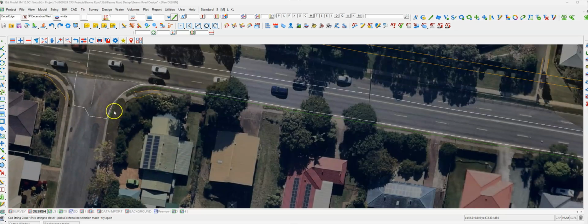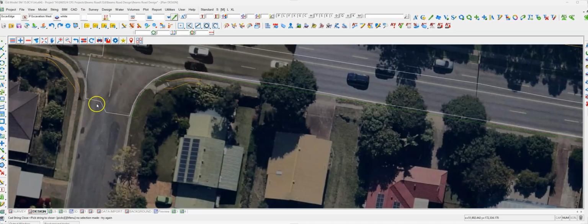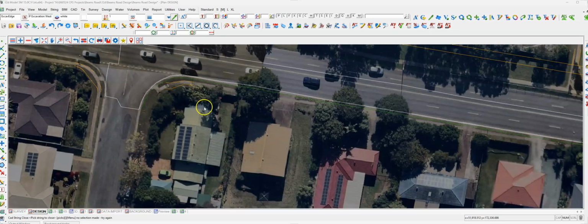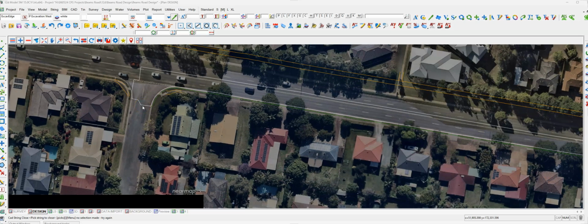And then I've made this other boundary, which is where we need to make sure we're quantifying and giving maximum quantity. And that is a boundary which is 300 behind existing back of curb, and that is for the excavation underneath of the profiling. So, like I said, make sure you get your boundaries right and that you're across what the quantity's got to be.